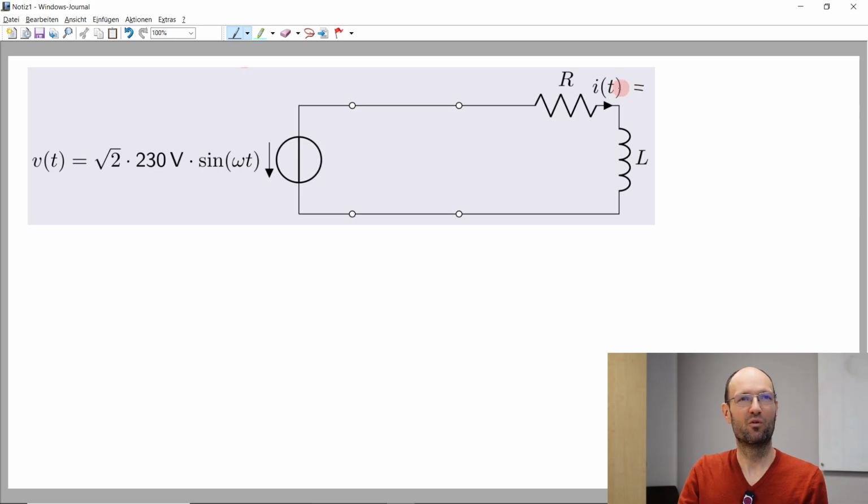So we would at first convert this into some complex phasor and say our source voltage here. And if we do it as some RMS phasor, we would just use the 230 volts. And if we start with some sinusoidal function without a phase shift, we could add it multiplied with e^(j0°), but okay, this is just 1. So we could also neglect this in our formula here.